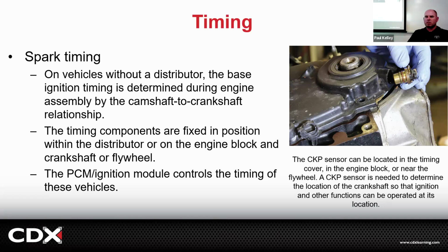They've done all their research and dynoed and tuned it at this elevation and that elevation and this temperature and that temperature with this fuel and that fuel and the other fuel. And we're constantly trying to get it advanced as possible without causing damage. So if we could advance it to 39, and at 39, that was the most horsepower, why do you think that the manufacturer might only go to 36 degrees?